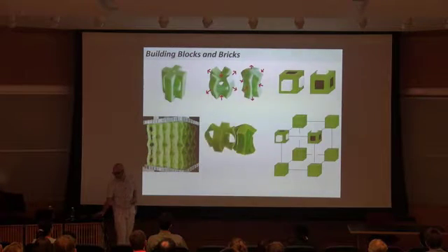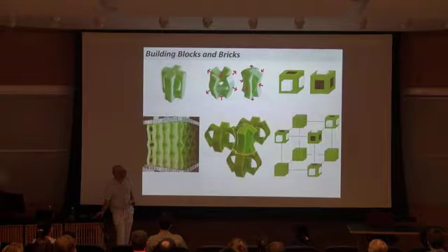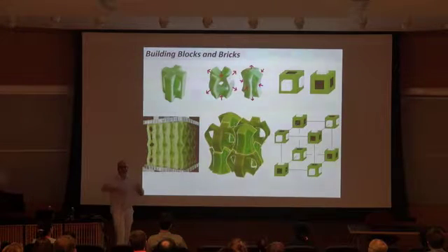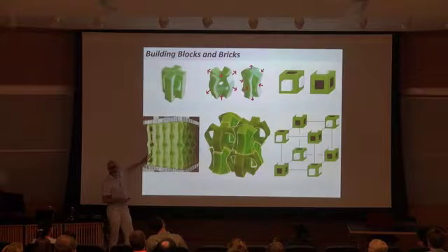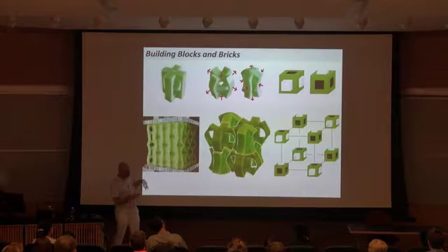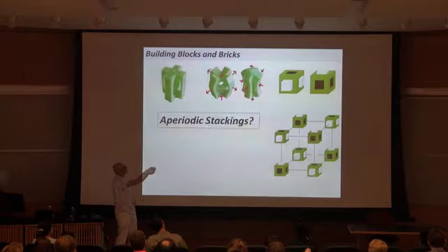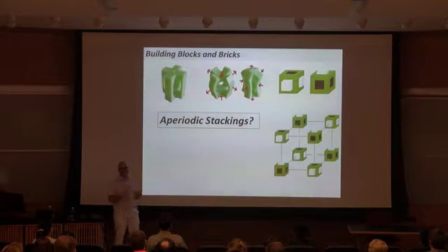It's clear that I can fit a deformed block that's deformed in the opposite way next to it. I can also do that below and behind. When you think about it, you can tile space with all these deformed blocks. That's the reason that this is the low energy deformation that you see, because the individual building blocks want to deform in this way, and they can do that.